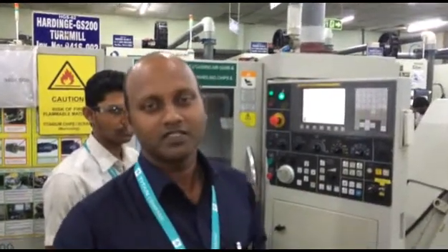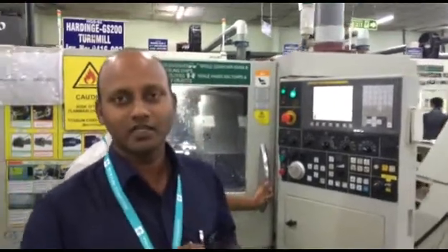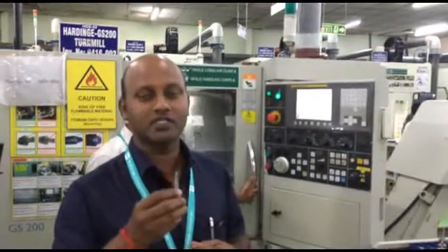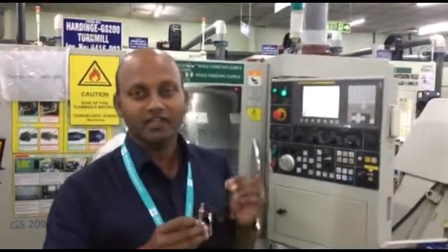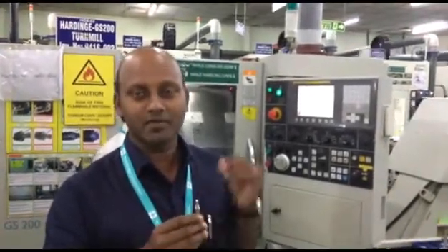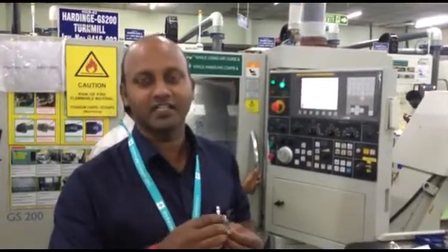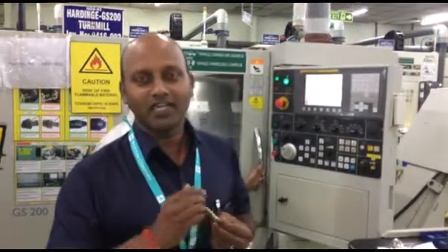The current speed is 700 revolutions per minute and the feed is 0.06 mm per revolution. The cycle time is 240 seconds. By using the variable search tool, we have redesigned the parameters, and the speed is now 1000 revolutions per minute and the feed is 0.086 mm per revolution. And now the new cycle time is 135 seconds. Thanks to Mr. Ram for guiding us through the project.